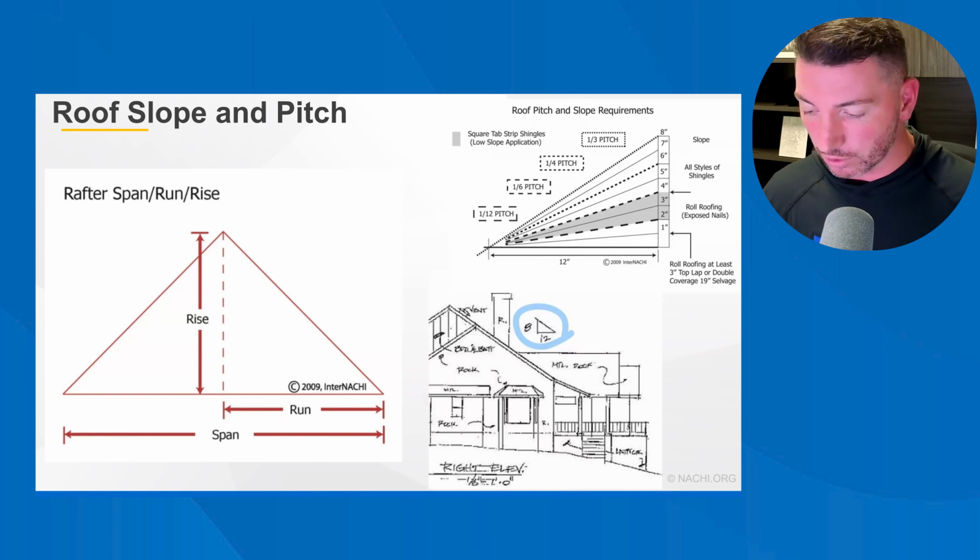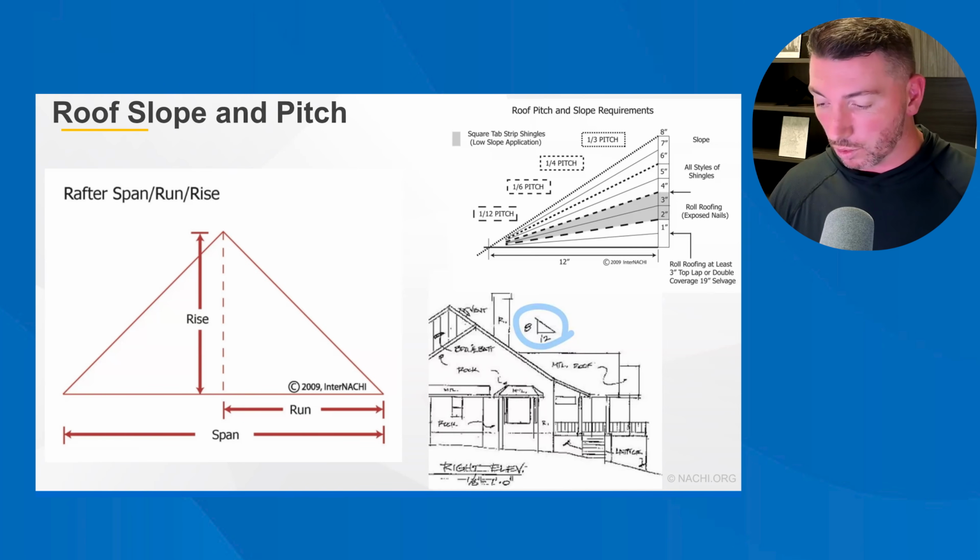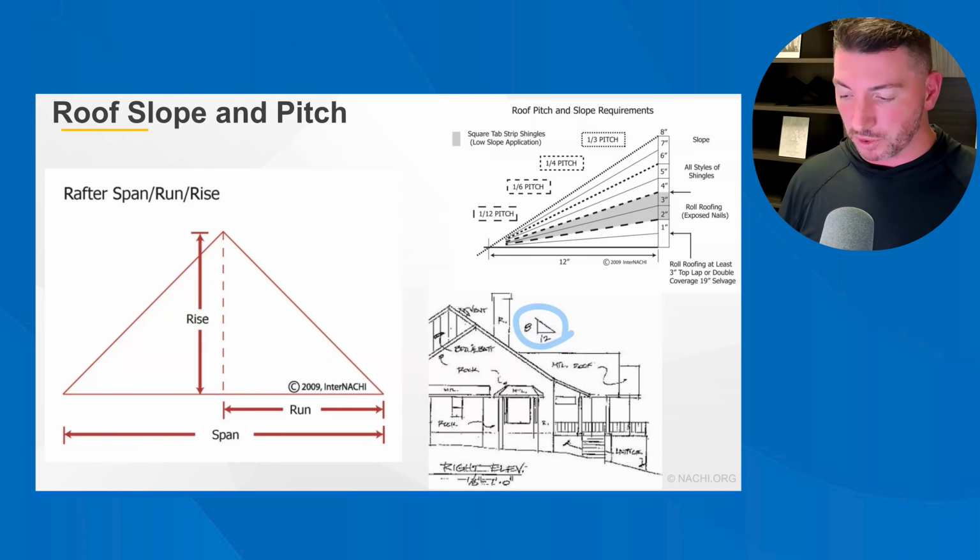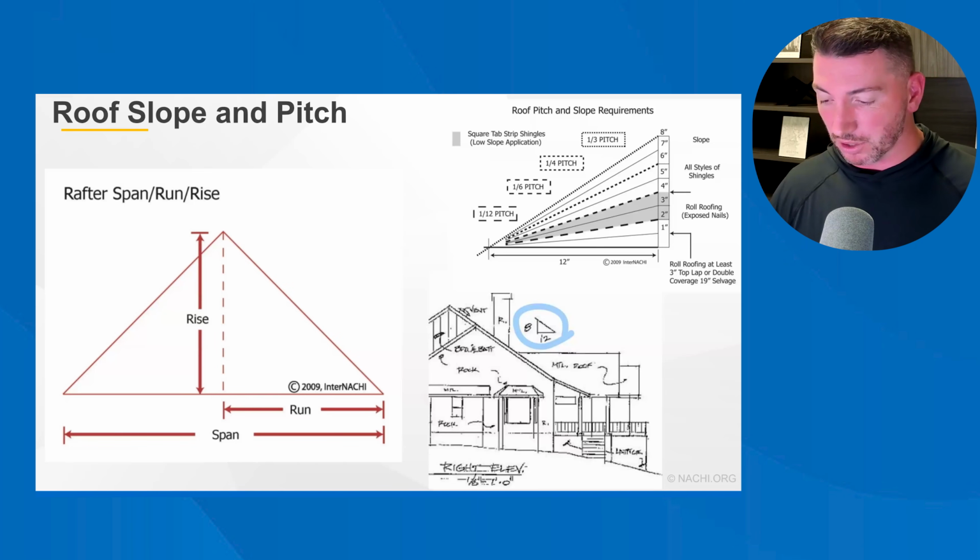Pitch is the incline of the roof expressed as a fraction derived by dividing the rise by the span, where the roof span is the distance between the outside of one wall's top plate to another. Historically, the word pitch meant the ratio between the ridge height and the entire span of the building, or the ratio between the rafter length and the building width. The ridge was typically in the middle of the span. This is no longer the case in a lot of modern building practices. The ridge can be placed pretty much anywhere in the span, like on a saltbox house, from directly in the middle to either span endpoint.